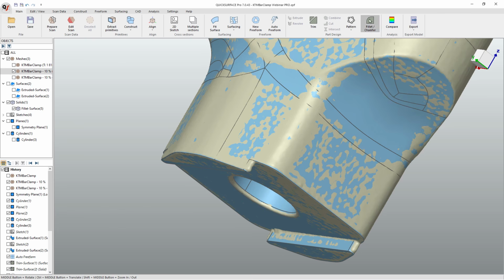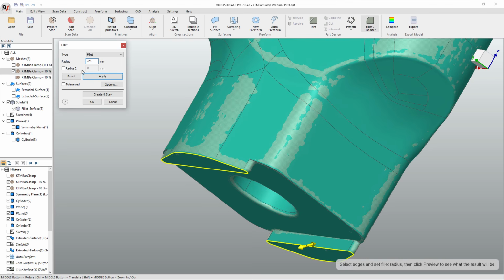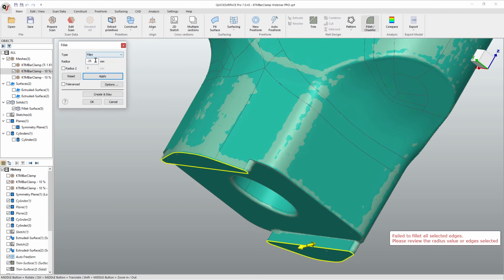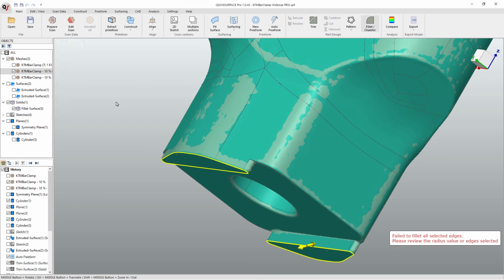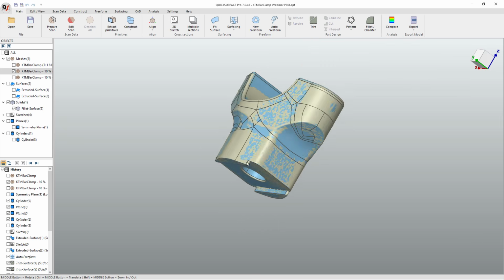It probably looks like there might be one more fillet on these bottom edges. Looks like both. Probably pretty tiny, just a deburr operation most likely. And it looks like it's failing. I'll go a bit smaller. Doesn't like wrapping around that corner there. So in manufacturing, this is most likely just a deburr operation on those corners. It doesn't seem to be liking the fillet. So what we could do is increase the radius of that fillet if we need to, but I'm going to go ahead and leave those corners sharp.